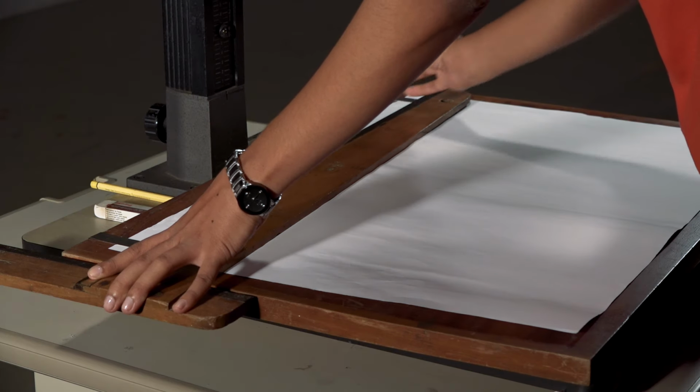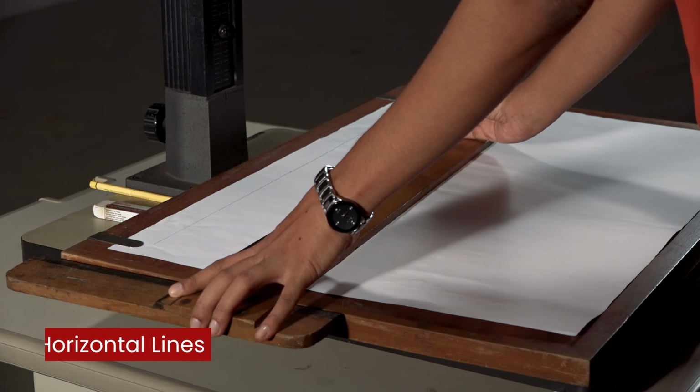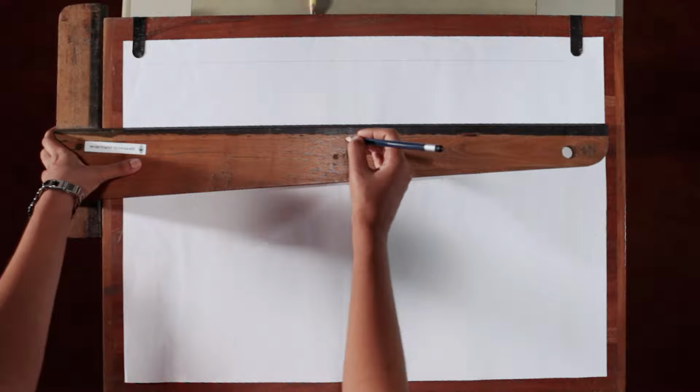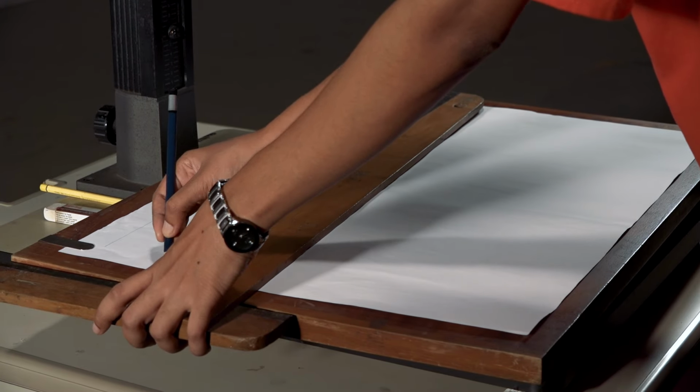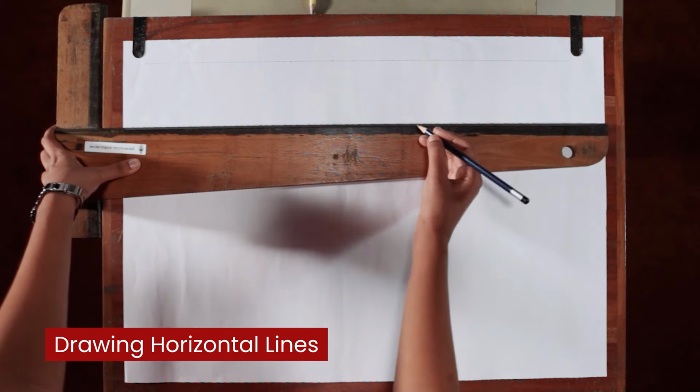Let us show you how to draw horizontal lines using the T-ruler. Make sure that you firmly press the T-ruler to the left edge of the board using your left hand. Here you can see a few horizontal lines drawn using the T-ruler.